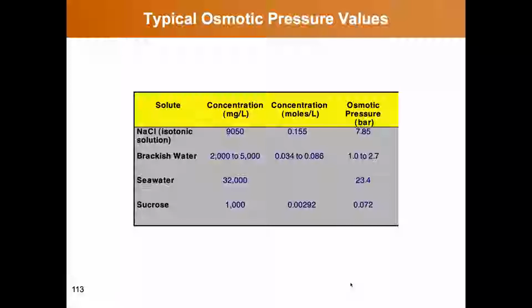And what that means is in order to purify water by desalination, you always have to have a feed pressure that's higher than the osmotic pressure. That's the point where you start to drive pure water against its concentration gradient across the membrane. And this is the energy, the cost that you have to put into the process in order to perform the separation. So desalination of seawater is typically carried out at pressures that are higher than about 30 bar, to have some driving force.